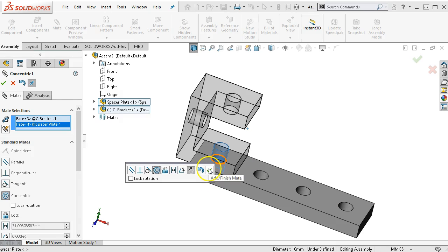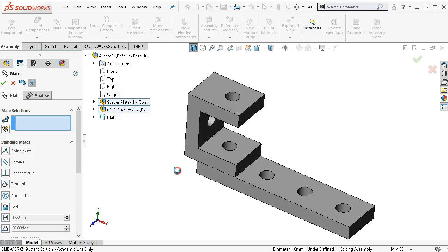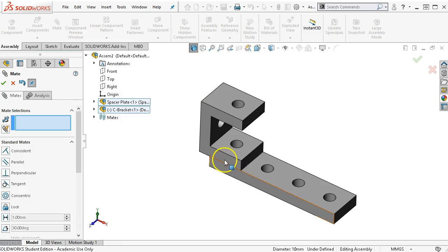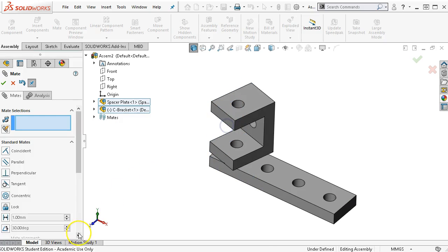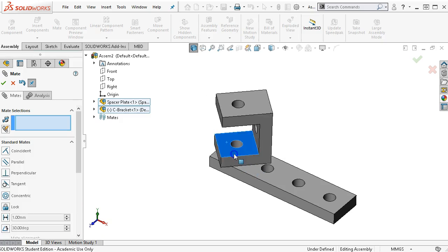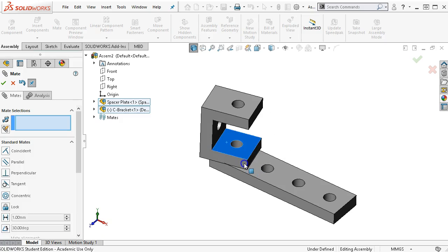Alright, so we've set a couple of our degrees of freedom, and on the preview it's showing me concentric, so cylinders are concentric, sharing the same center. And we're not able to move back and forth, front to back, left to right, up and down. But we still have rotation. So our 6 degrees of freedom are movement linear across X, Y, and Z, and then also rotation about X, Y, and Z. If we control all 6 degrees of freedom, then we have fully stabilized this part.